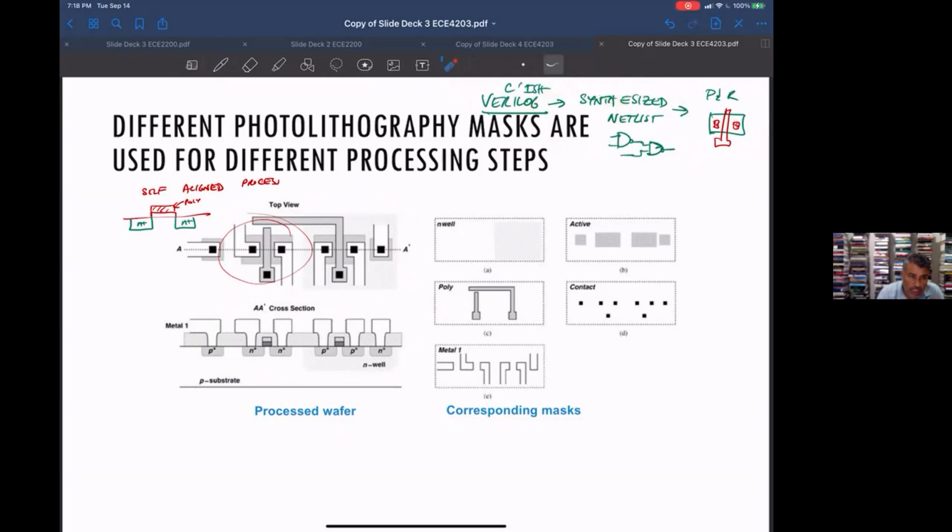But you basically have to do hand drawing when it gets to the most high performance part of the circuit. So let's say you have stuff running at multi-gigahertz through your chip, like data paths. Some of those you end up having to do by hand, or IO circuits.